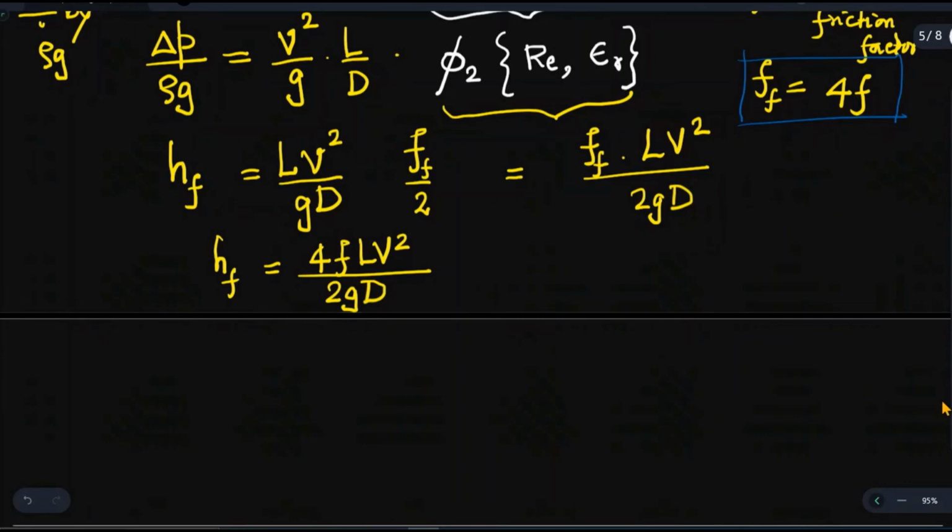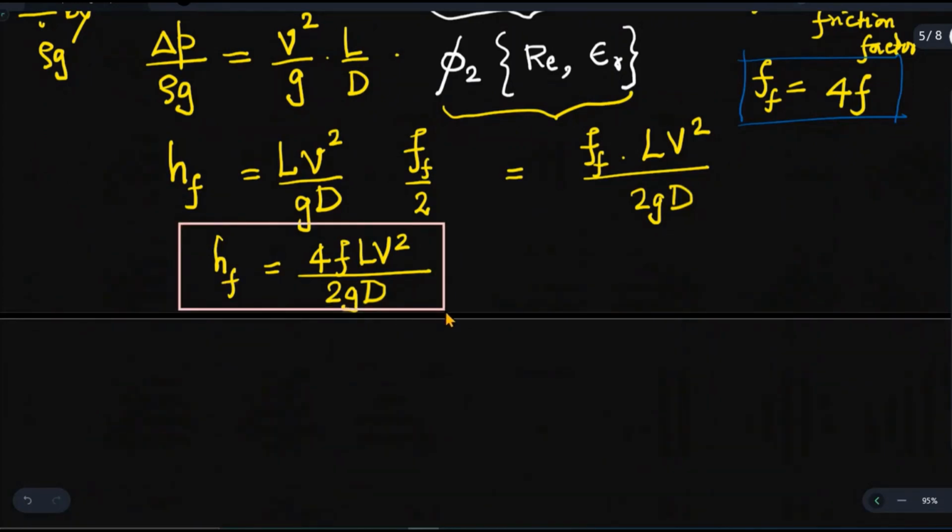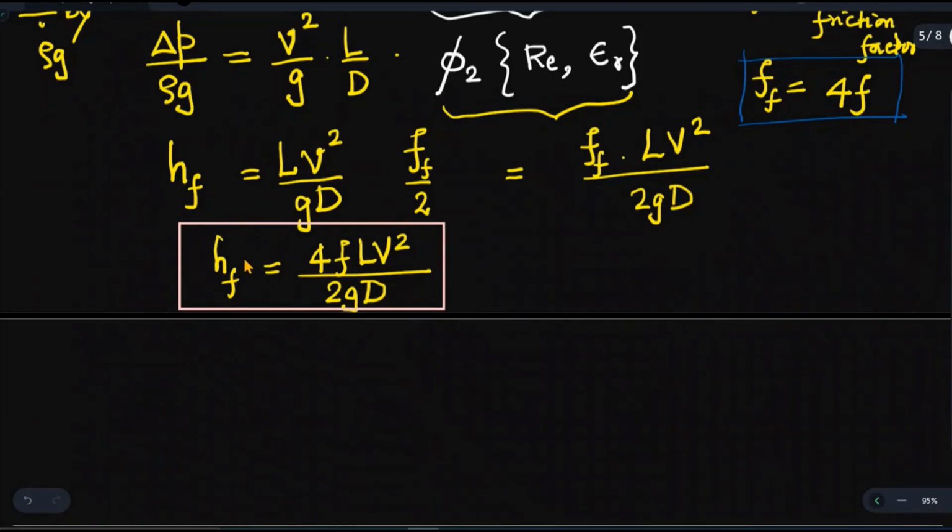Finally, by using the Buckingham Pi theorem, by obtaining the functional relationship involved in this physical phenomenon, you may be in a position to arrive at the Darcy-Weisbach equation. That is the final answer to the question. We found the prominent dimensionless groups and ultimately Darcy's equation. How it leads to Darcy's equation, you have to practice well. Okay, then. Thank you.